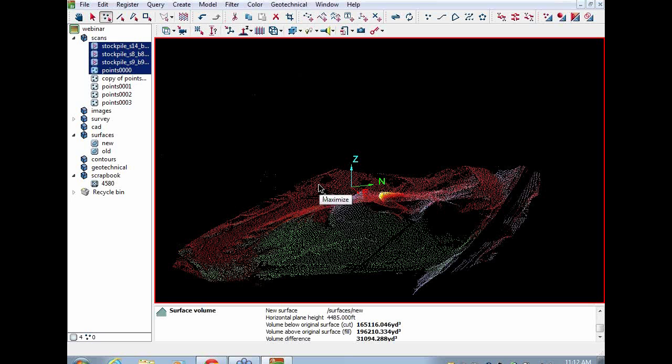Is there any material that cannot be scanned? There's not a material that cannot be scanned. However, there are materials that cannot be scanned at the same distance. Coal, being a much darker material, does not have the same reflective values as something like granite or a lighter rock color. So it can still be scanned, but not from the same distance. You won't see that 1,500 meter return. Probably about 1,000 meters is all the further you could scan coal from.